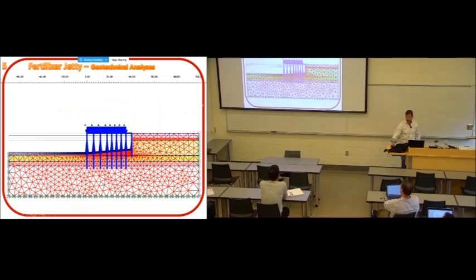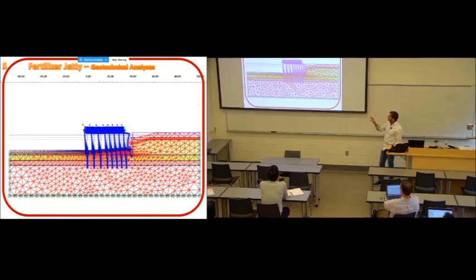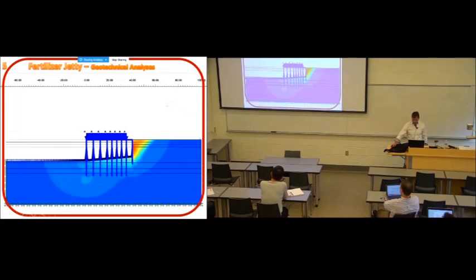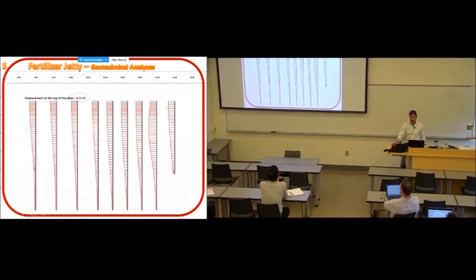And when I did another analysis with Plaxis, you see the deformation, how it's going to move laterally and some bending on the secant pile wall in the back. When I discovered that the two results are very close, I was very happy. Actually, I was surprised, because it is very rare to have a match like that: 6.6 and 6.3 centimeters using two different software.